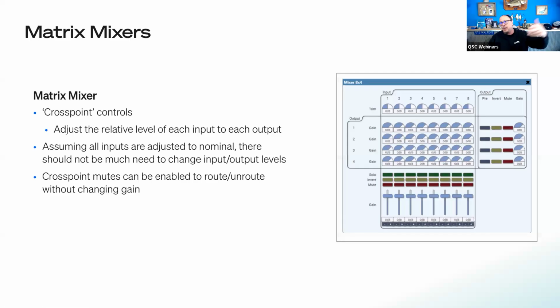That's why we set the input mics, the analog inputs coming in, the program audio sources, or heaven forbid, someone's still using a hard codec or something like that. You have to make all of them be -20 dB full scale, because if you're trying to fix it in the mixer, it's going to be a mess. So just know that's a key indicator if you're making a bunch of adjustments in here. Typically what you'll see from me is my AEC output for my reference. On the output side, if this is the output for the AEC, I might give it 3 to 6 dB of a little bump of gain coming out of the mixer. But cross points are almost always hovering around 0.